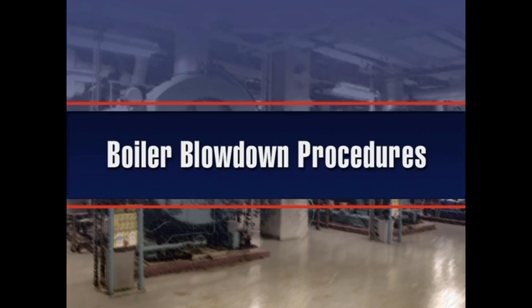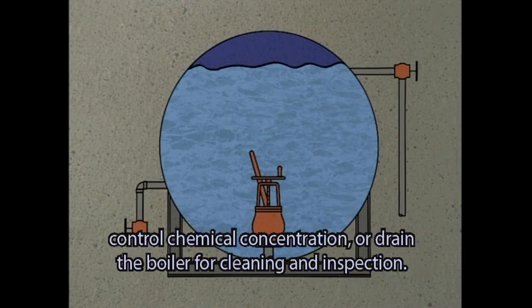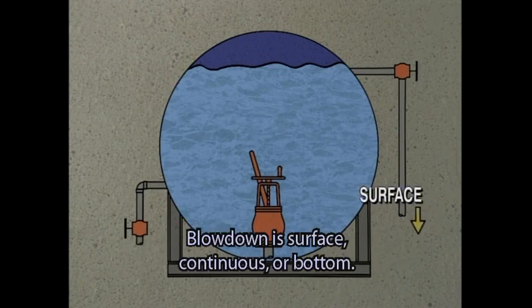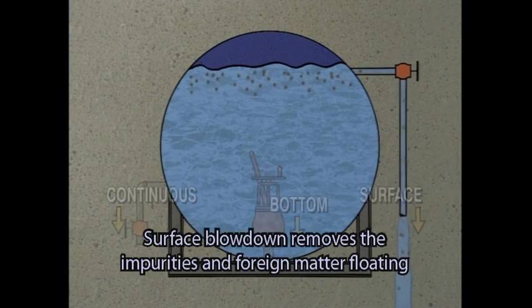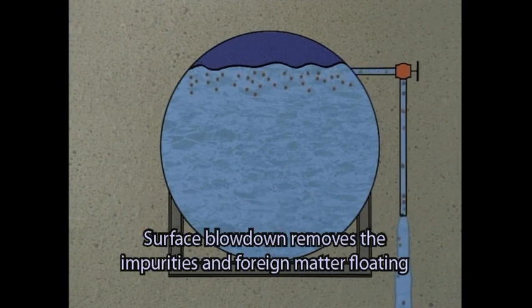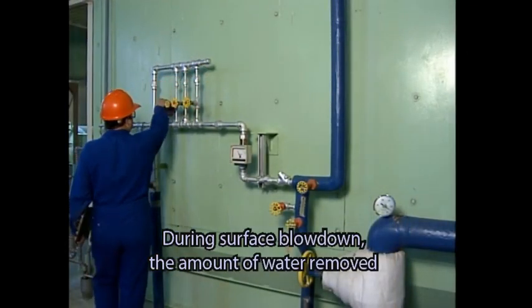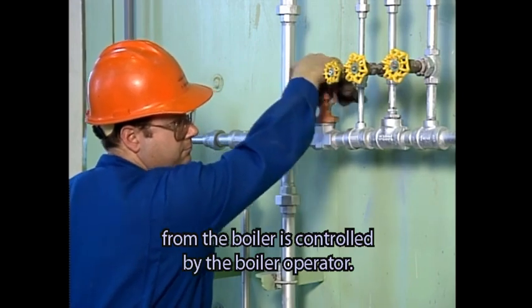Boiler blowdown procedures. Boiler blowdown is used to remove sludge and sediment, control high water, control chemical concentration, or drain the boiler for cleaning and inspection. Blowdown is surface, continuous, or bottom. Surface blowdown removes impurities and foreign matter floating on the surface of the boiler water. During surface blowdown, the amount of water removed from the boiler is controlled by the boiler operator.